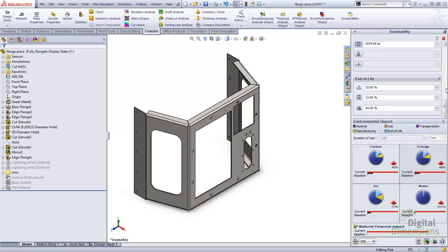We can take all of these different parameters and do some comparative analysis. So we're going to leave the defaults using this exact geometry and gauge size with our stainless steel material, and then we can look at some trends. So again, let's set our baseline, and now let's change our material here to maybe plain carbon steel.